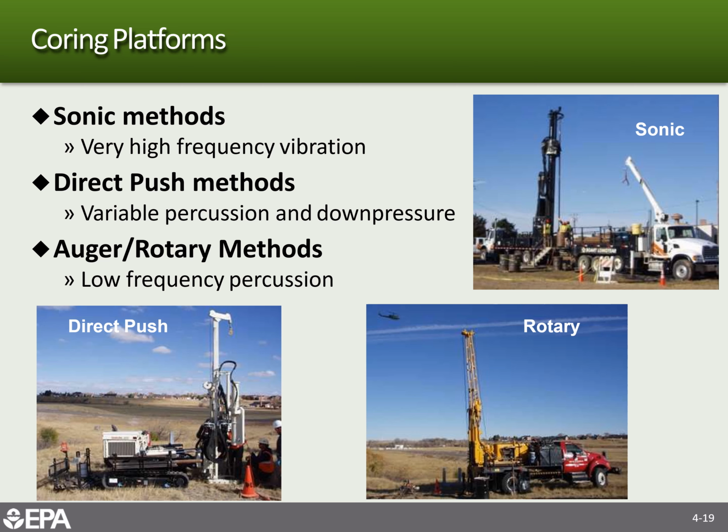Rotary has a thing called the split spoons, and the cores are in a little better shape, but sometimes the production is a little slower than with sonic. But sometimes the conditions are such that you need to use the rotary, because oftentimes you have to use water with the sonic, and that can dilute out the fluids in the core if you want to take some representative samples.